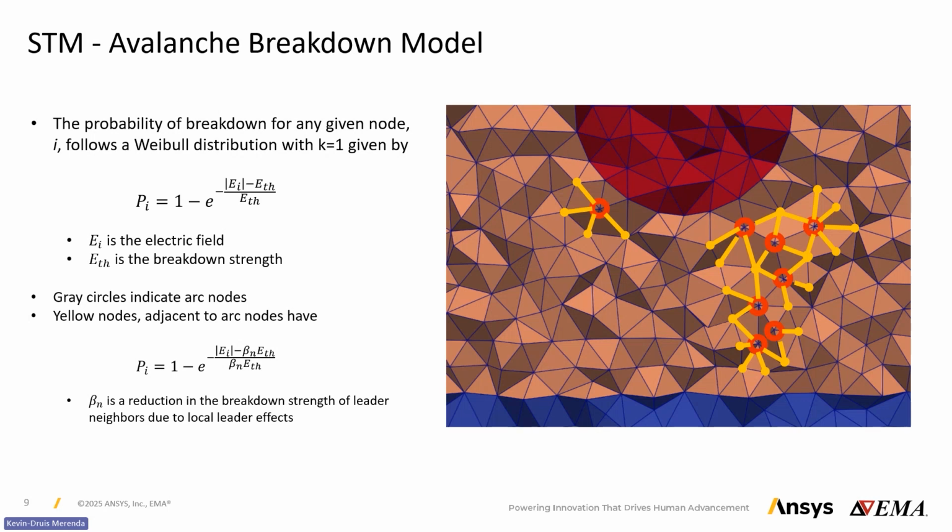And we are going to change its conductivity to what we call the post-breakdown conductivity of the system, so that at the next time step, this mesh element is now conductive, similar to the electrode or whatever we set up as the material conductivity after breakdown. The fields are going to be updated and consider this element as a conductive path. So when we iterate through this process over time at each time step, we are going to be able to propagate this discharge through the system.